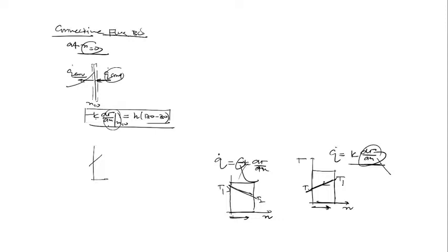So listen, yes, it's very clear. Here also I should write the minus sign. Why? Here in this case, as x increases temperature decreases, so dt upon dx is negative. Then negative becomes positive, so heat is transferring in the positive x. Clear? Here in this case heat is transferring in the negative x. So q should be negative, and negative is only possible if the minus sign is there. Yes or no?